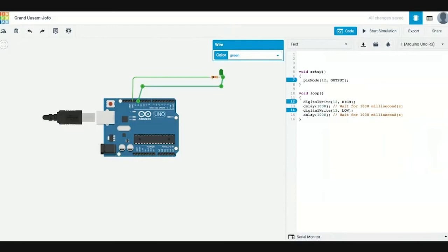Why don't we create a variable and just pass that variable to each place where it is required in the parameters of pin mode and digital write? To declare a variable, let's go to the global variables section of this sketch. The global variables are declared at the top of your sketch.